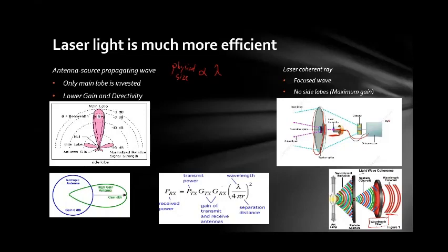And actually, this is the very reason why modulation was invented as a technique. Say, for example, we want to send a speech signal, and speech is roughly from 20 to 20,000 hertz. So let's say the signal is at 1,000 hertz. This will require a very large antenna, maybe kilometers long. So it's not really practical. And that's why we modulate it using a carrier signal that has higher frequency.